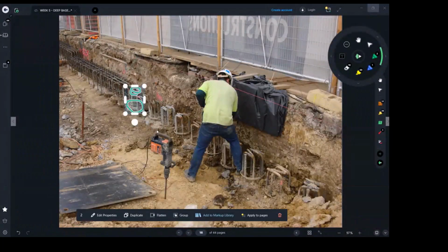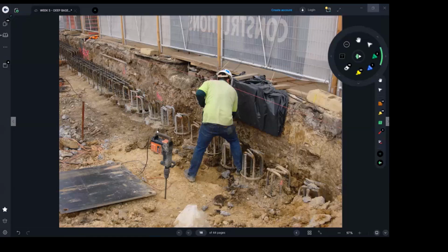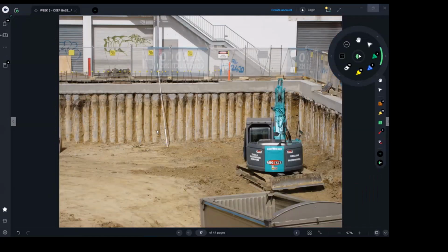Okay, any questions? This was just pictures for the second type. This is another picture, and you see we can even achieve higher depths here. It looks clear to me, 3+ meters deep, right? Because the piles are doing the job here, the contiguous piles.